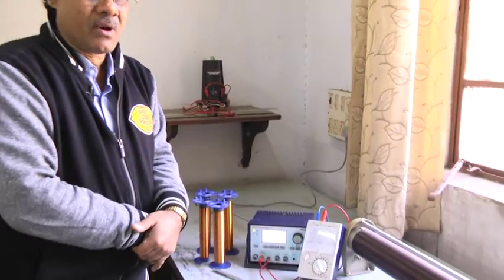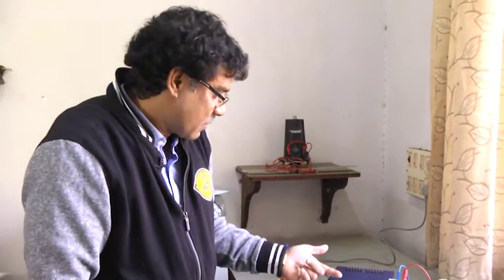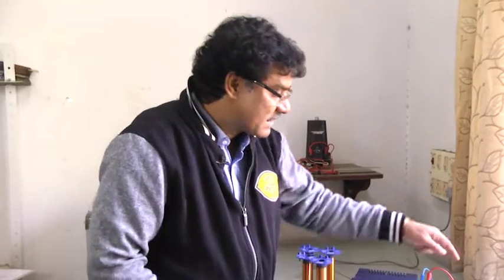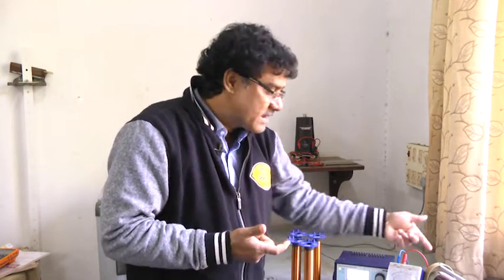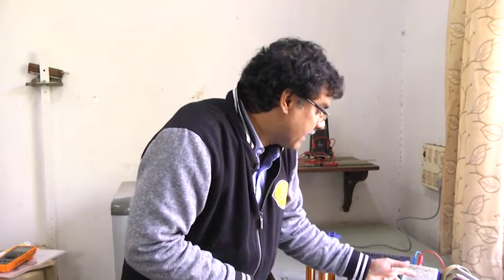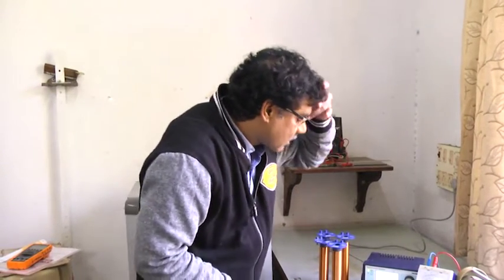Now because I told you that I have to keep other parameters constant, right? So basically I have to keep this current at 150 milliampere, right? Now the question is, when I change the frequency, why does this current decrease? That means resistance of this circuit is increased, because this is the solenoid, the inductor. So the inductor's resistance is omega L, 2 pi f L, where f is frequency. Now frequency is increased, so this inductive reactance is increased. That is basically resistance. So resistance of this solenoid is increased, and that's why current decreased. So I have to apply higher voltage to bring it back to the 150 milliampere. So that's what I have to do now.